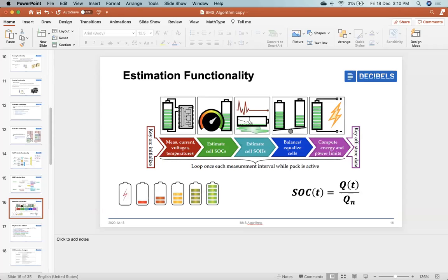So cool. We have another question. In India, we use 48, 72, 60 volts. Why not go for a higher voltage? Okay, a very good question, Piyush. The voltage architecture depends on the current ratings you would like to handle, and also on certain regulations. If you go for a higher voltage, like 72 or more, you need to ensure higher voltage safety systems, because that's a very critical system.